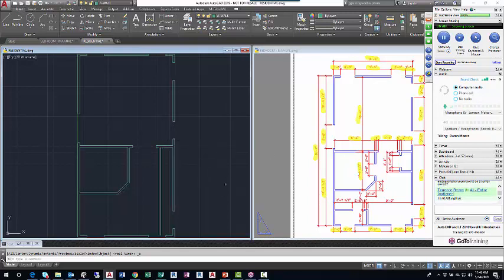Cool. I'm going to finish off this closet. This closet requires two 2-foot 6-inch offsets. So I'll go offset 2 feet 6, enter. I'll left click the interior. You can kind of see the dimension touches the interior line. I'll left click the interior horizontal line, move down the screen, left click, and then I'll left click that new line I made. They're both 2 feet 6. I'll left click, move down, and left click. So there are my 2 cutting edges.